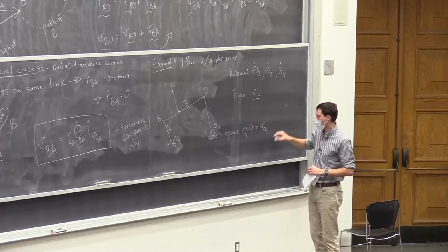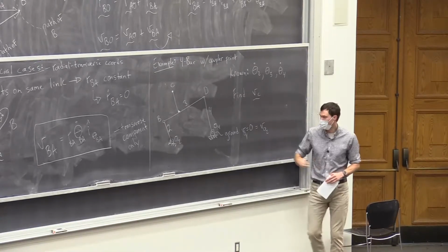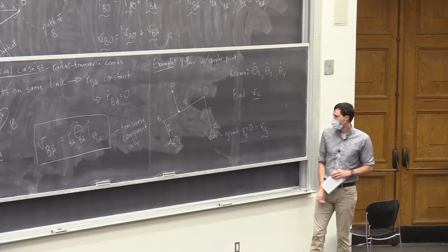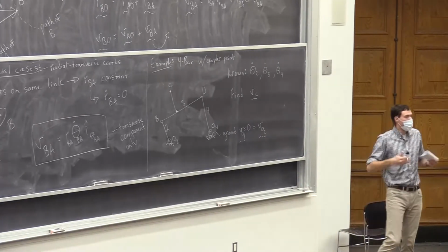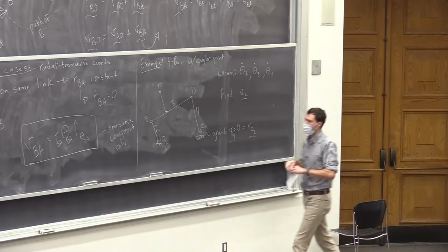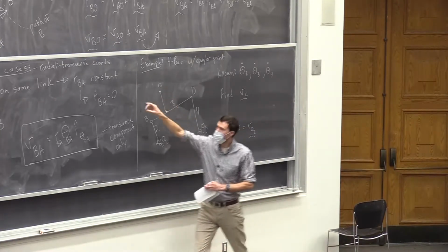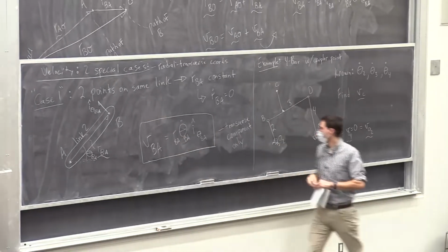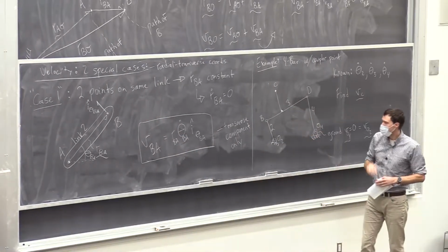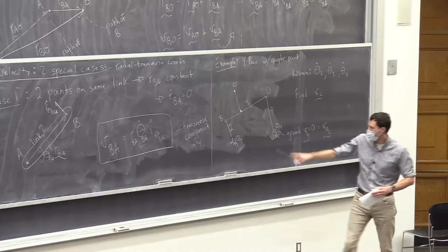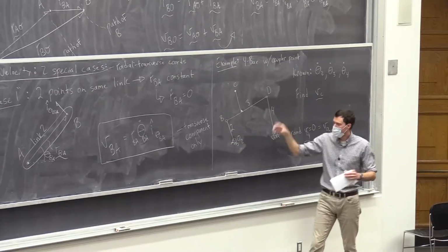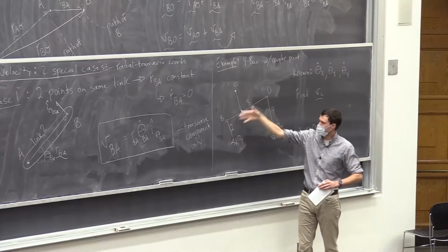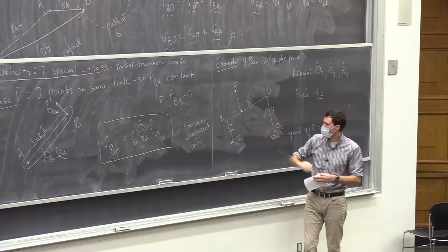And all of those ground connection points have a 0 velocity. So we can start our analysis at either of those. And we're going to try and step through our mechanism and use case 1 examples to build up our velocity of C. And so you'll have 2 choices here. You can start at O2 or you can start at O4. I'm going to choose O2. It's physically a little closer, easier to draw.